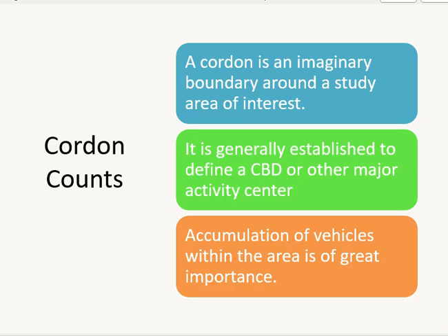The other thing is straight traffic is more accurate as well. You are either entering or leaving. There is no turning here. At an intersection, you may have a chance that somebody is taking a left turn and going back into the area. We don't know. Somebody is taking a U-turn and so on.